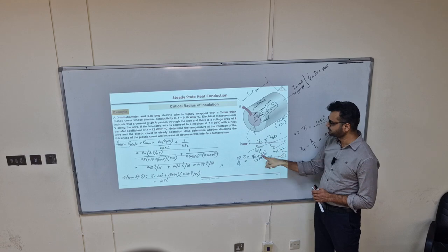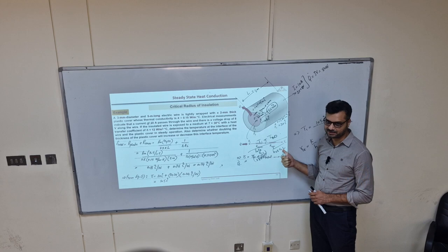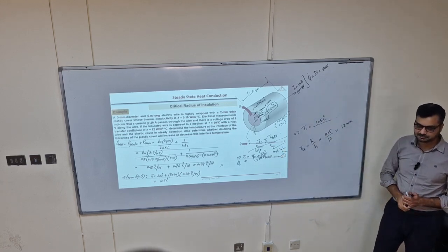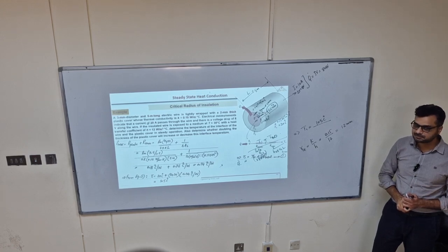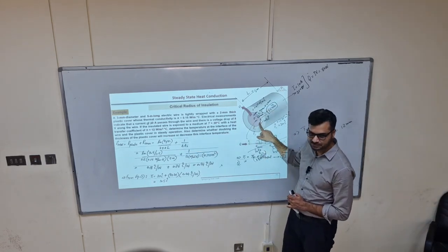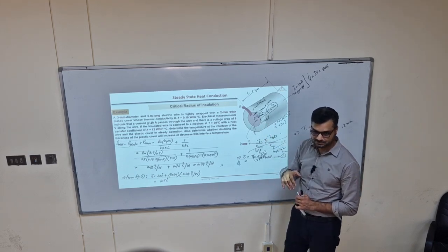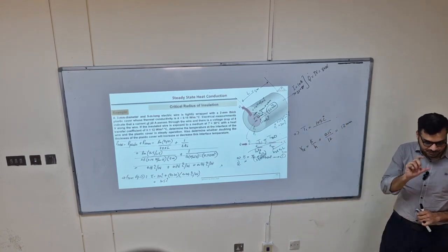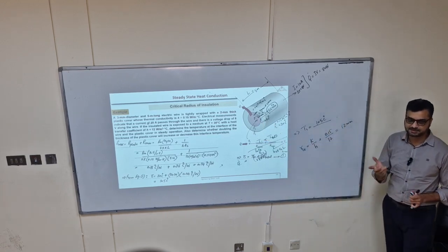But the effect of Q is different here and here. Which one is dominant? Yeah, this one is dominant, convection. But there's still the same Q dot. It's fixed, so we don't control the heat transfer losses. We didn't want to control that. We want to control this temperature. This temperature should not be 105. We want this temperature to be lower. Heat transfer is fixed, so how will Q change? But what you can do, you can control this T1. And by adding insulation, yes.